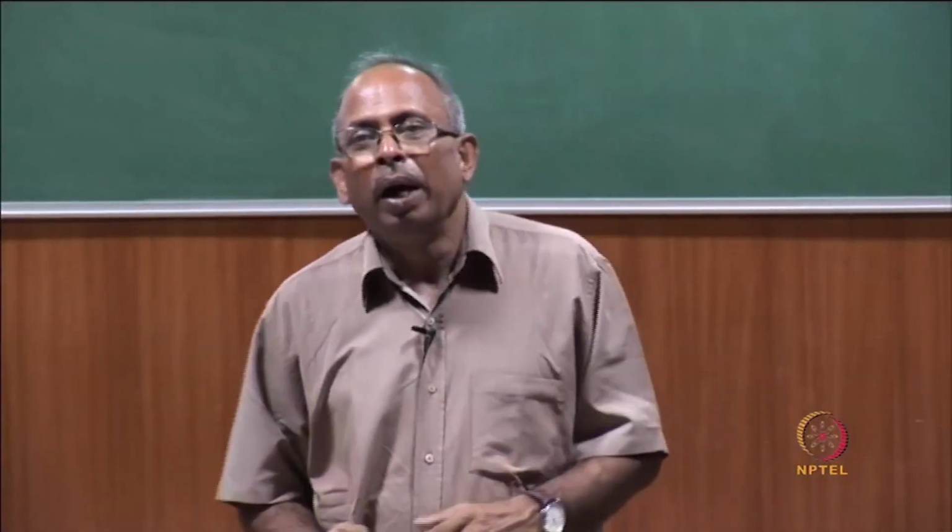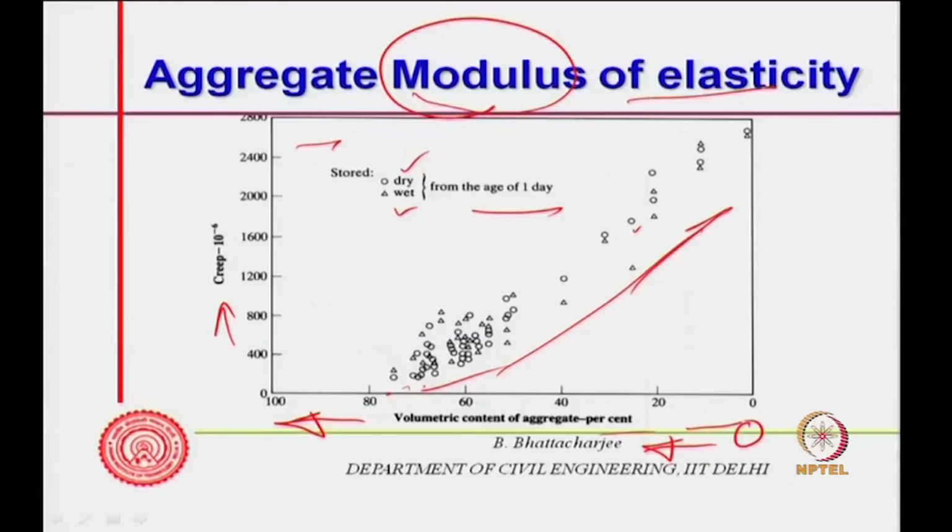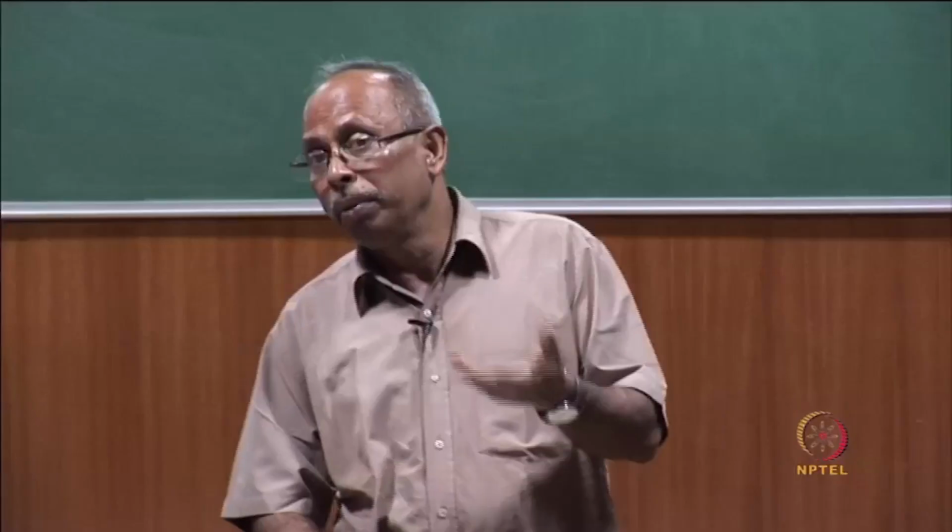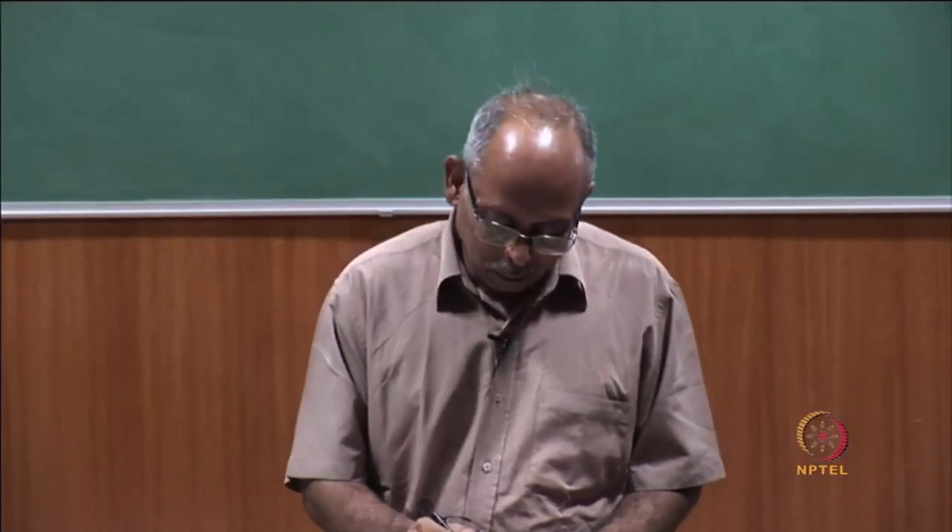So, it will not contribute to creep, while paste will. Although it is not really related to modulus of elasticity, it is related to the aggregate content. Finally, it affects the stiffness of the system, because more aggregate means a stiffer system, and the stiffness will be governed by the aggregate modulus.